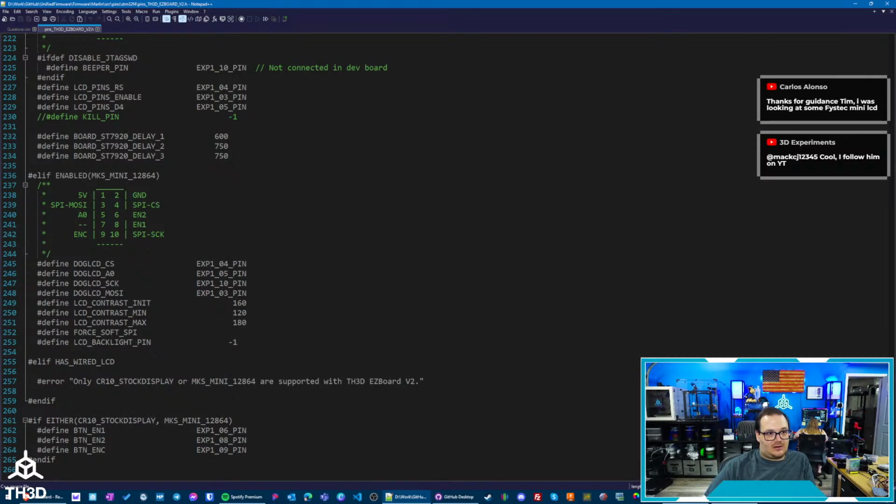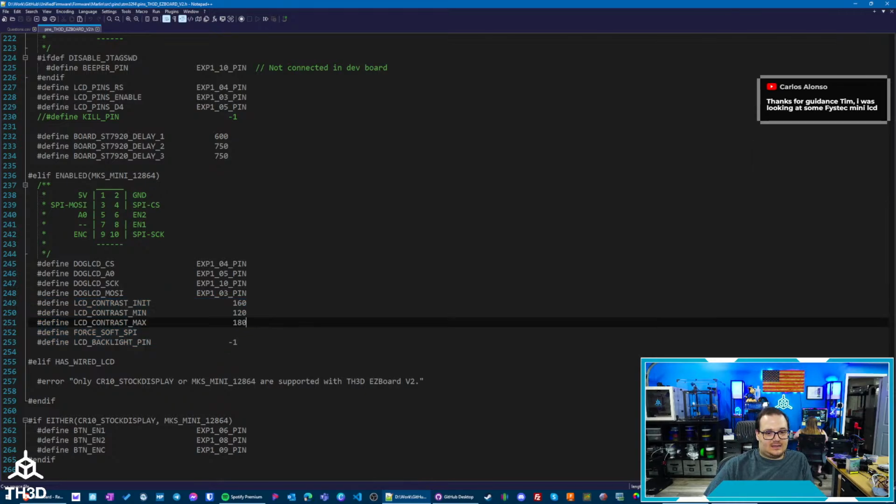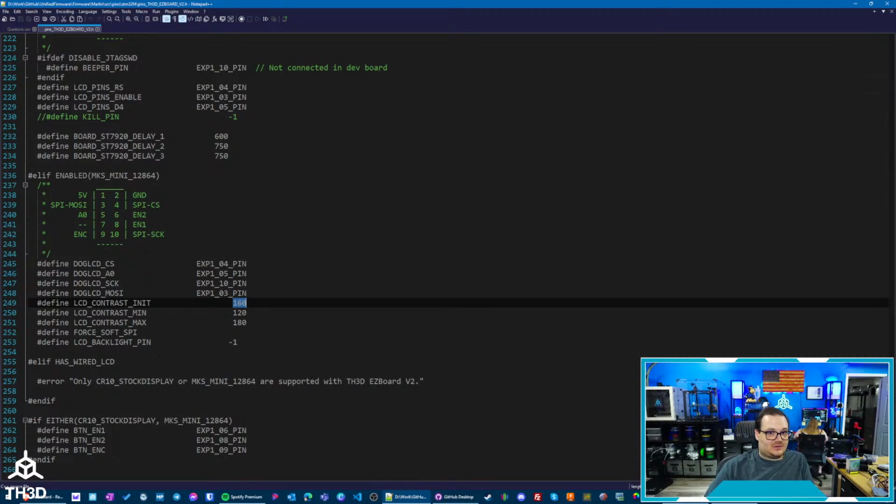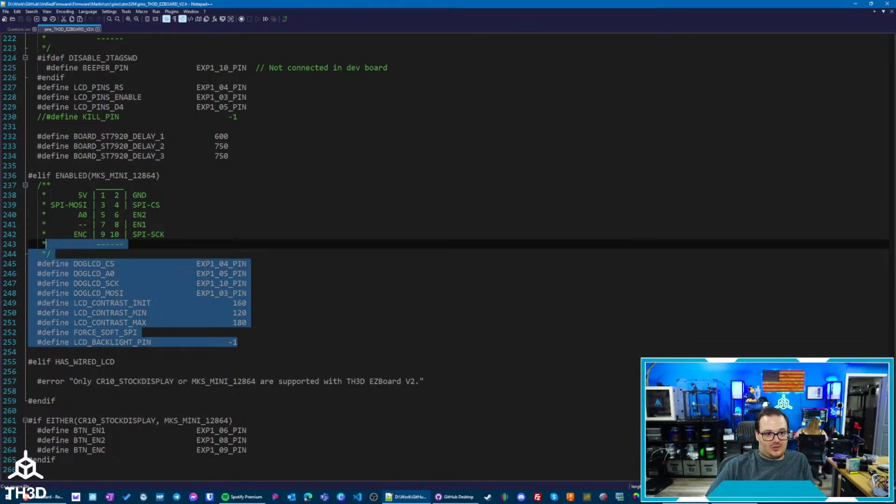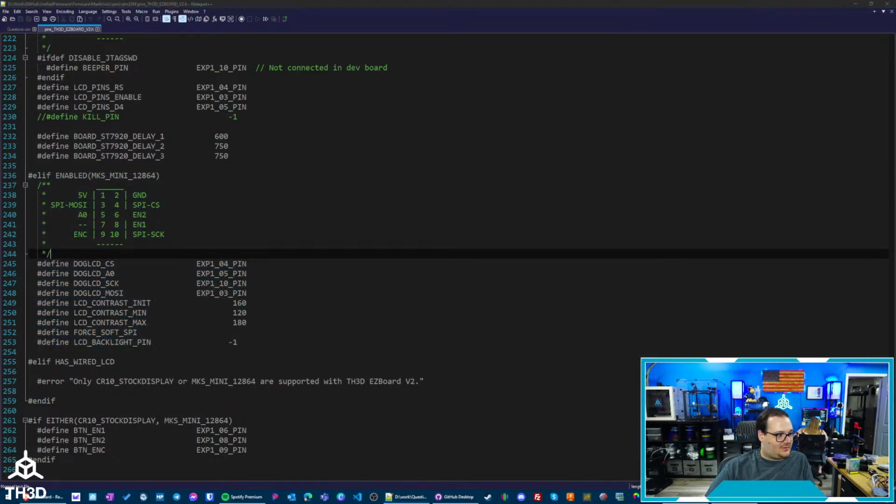The other thing, if you guys are using the mini panels, this is something that is usually on the mini type panels, is the contrast settings. So one thing to look out for if you are messing with getting one of these running on any board is the LCD might be working, but it might be very dim. And so you might have to set the contrast setting to a default. You can see here, for the CR20 display, we actually had to use an initial contrast value of 160. Now, the thing is, this value is also stored in your EEPROM. So if you don't clear your EEPROM, the contrast default will be there, but the EEPROM might have a different setting, making it too light where you can't see it. So there's all these little gotchas that I've learned from doing this stuff over the years. So hopefully that helps out.